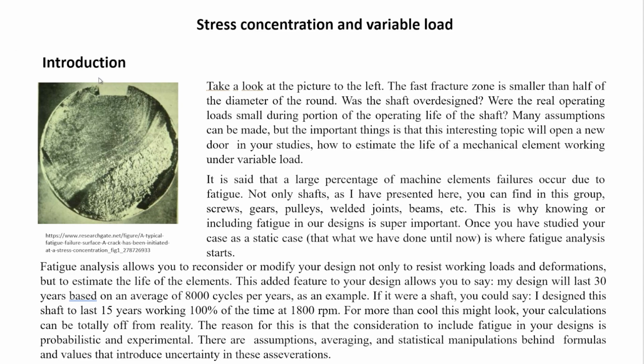And the function of a keyway, we should know that, is to hold a key here. And this key, its only purpose is to be used as a reinforcement to avoid any relative movement between this piece of the shaft here and whatever you mount on top of that.